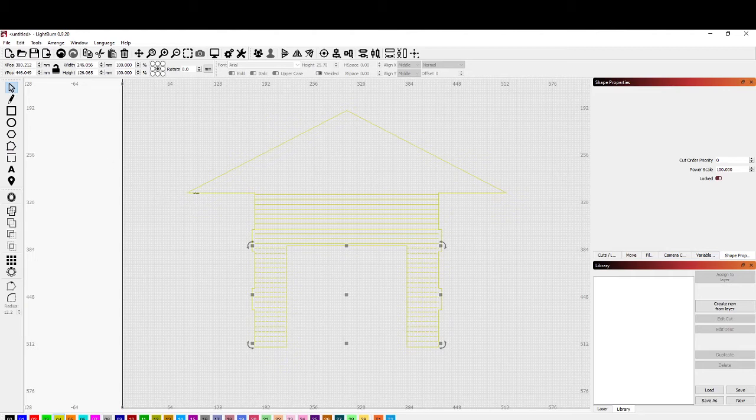I'm going to click on the building for a minute, and go to the node editing tool. And you can still change this roof pitch, so I'm just going to drag this in a bit. Oops. Yeah, that's another thing. I use shift to try and keep this on the same line, but if you click and you don't take your finger off shift, see now they're both gone red, now it moves them both together. So really we don't want that here, so I'm just going to click off of it so they're not red, and just shift and click this one, bring it in.